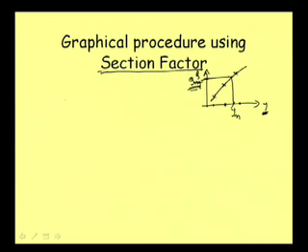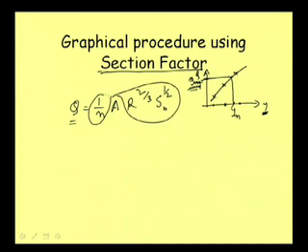Okay. Now, let me write first Q is equal to 1 by n, then we can write it in a different form, A R to the power 2 by 3, means including this area into velocity, A R to the power 2 by 3 and S_b to the power half. Okay. Discharge is equal to area into velocity. Velocity means this part and this 1 by n, and this part basically comes from Manning's equation, and this is area into velocity.